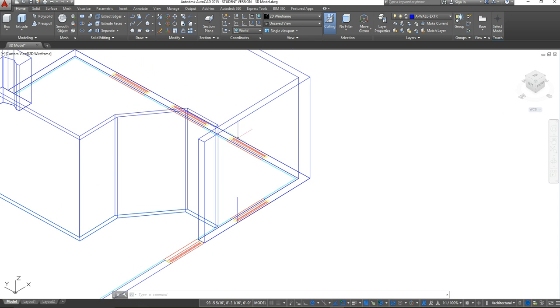So it looks like we don't actually need to specify front in our coordinates before we can create this line. So you just want to create that line first, and now this is where our coordinates become important. And so we can go to visualize and then go back to it, or you guys can actually access that from this ribbon as well. So we're still in our home tab, but now we're going to go all the way over to coordinates, and again we're going to click down and we're going to go to our front.